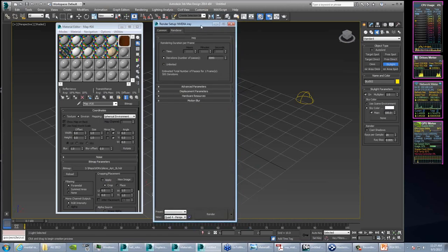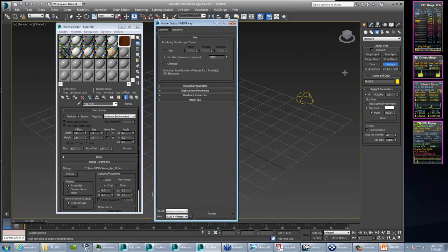Interior, it depends on the content of that scene, what you might need, but 3,000, 5,000 is pretty typical. In some older versions of Iray, there's been scenes where we've set it to 10,000, 15,000 or more, just to try to reduce the noise as much as possible. The newer versions of Iray do a much better job per iteration of working on your image. So you don't need extreme high numbers for the iterations.